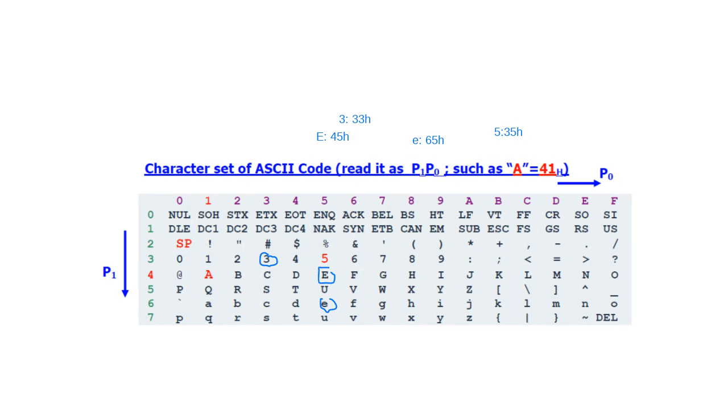One thing is the relation between capital letter and small letter, and one thing is about the numeric data that we put from the keyboard. If we press 3, 7, 8, 9, whatever it is, the ASCII value is 30H plus that number. So if you subtract 30H, then we will get the actual number. Okay, now it's about this one.